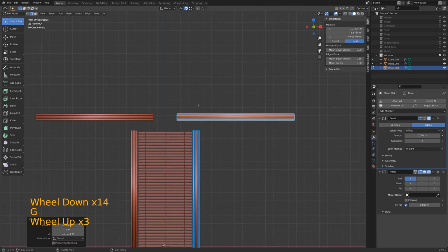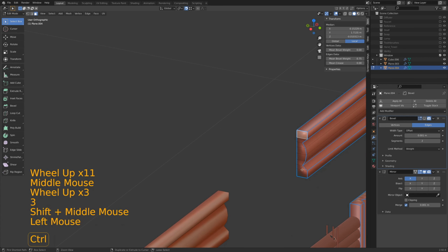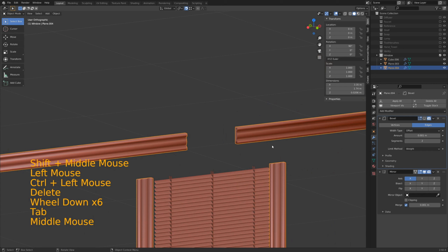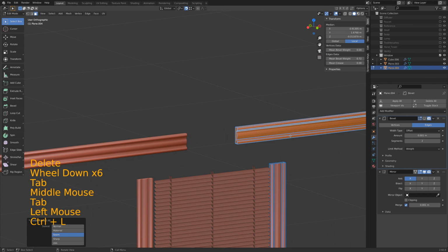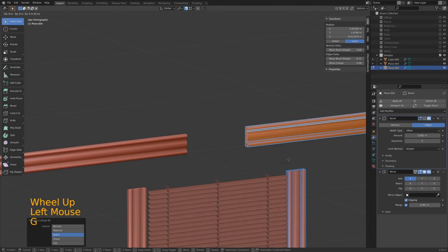move that up here, and we want to be able to see these faces here and delete them. So Control L again on one of these, and ensure that the mirror has clipping enabled so that when we move it on the X, they can't go past.